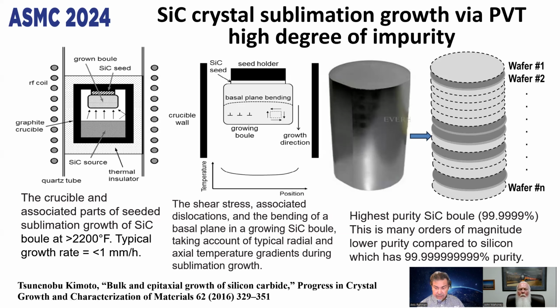The crucible is not totally inert at those temperatures, and some impurities can be introduced even unknowingly, without any reason, from outside. Also, this is induction heating with an RF coil that goes around the crucible, and because of that heating arrangement, the temperature may have local variations within the deposition zone that are not easy to control.